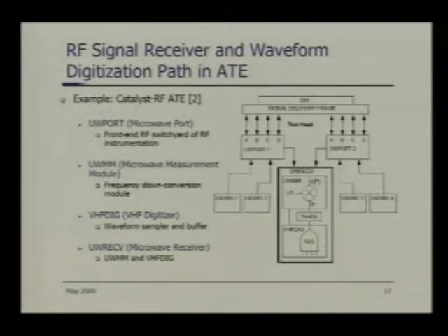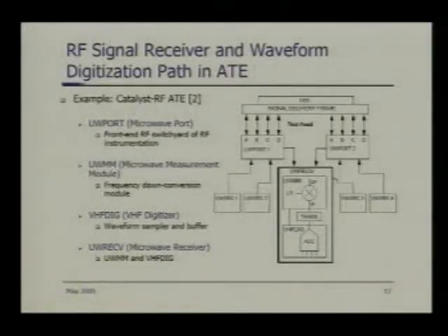So with this RF signal, you have 1.5 gigahertz going in, and you program the LO so that you get some frequency which you can digitize for data analysis purposes. Here you program a local oscillator signal which brings the frequency down to, say, 100 megahertz or 50 megahertz, which is good for digitizing and running all kinds of frequency domain analysis like FFT and peak search and so on and so forth.